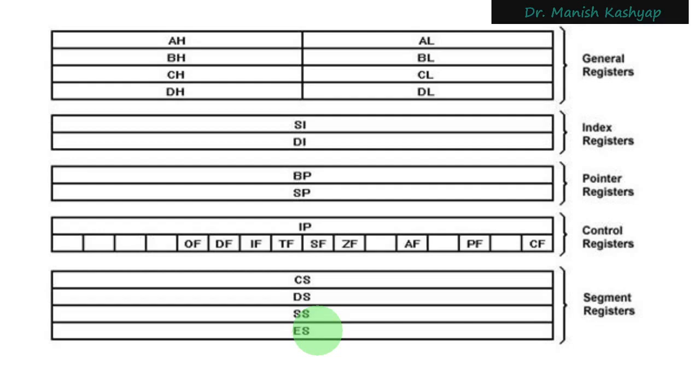location. But there is a restriction on the starting address of code segment, data segment, stack segment, and extra segment. If you see the hexadecimal representation, the address will be of 5 hexadecimal digits for the externally interfaced memory, and the restriction for the starting address of code segment, data segment, stack segment, and extra segment in the external memory is that the last hexadecimal digit has to be 0, or the least significant hexadecimal digit has to be 0. That way we are only left with 16 bits.